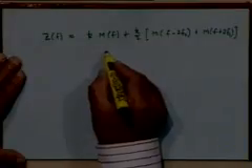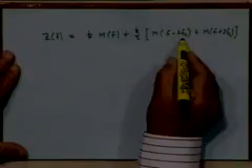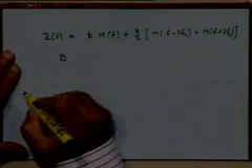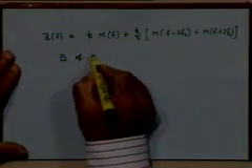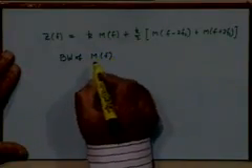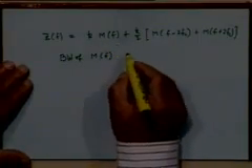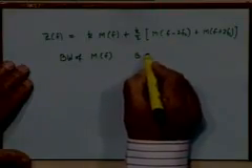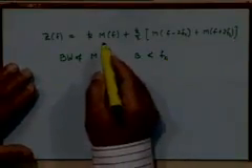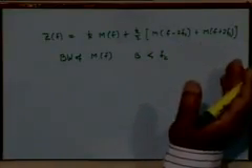And as we know, if fc is suitably chosen, what is the requirement? That the bandwidth B of M of f, the largest frequency component in m of t, satisfies the condition that B is less than fc. Then obviously it will also be less than 2fc, and these two spectra would not overlap.